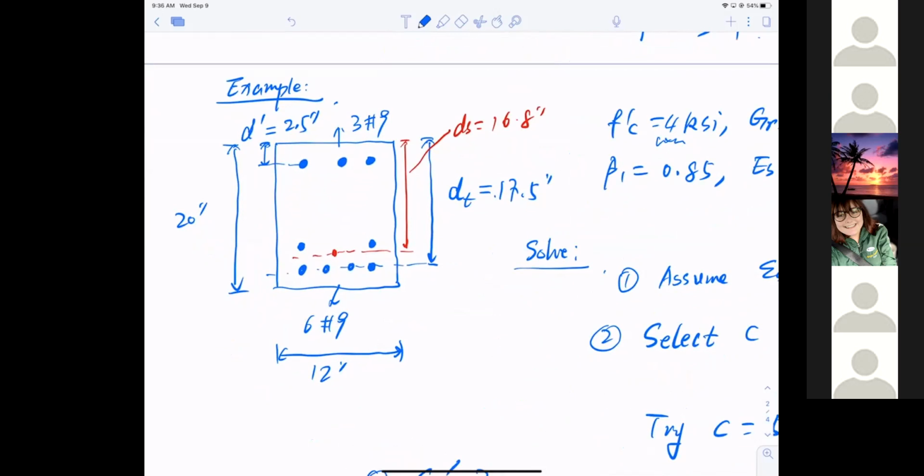So think about it. These bars at the bottom, do they take care of tension or compression? They'd be taking the tension. Right, so these are tension bars. So it'd be the 3 up top. That makes sense. So these are the compression bars. I know we forgot, so that's okay. Just remind us.